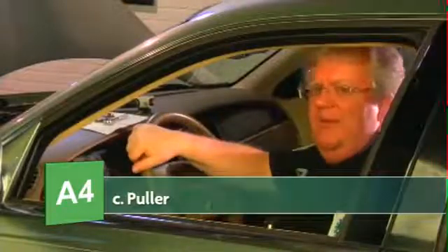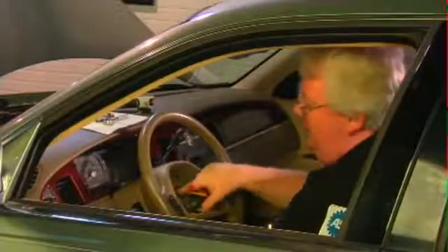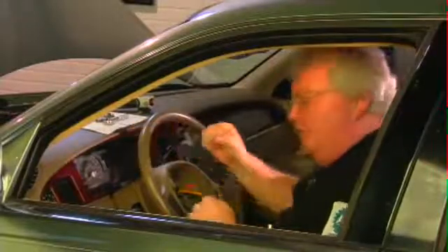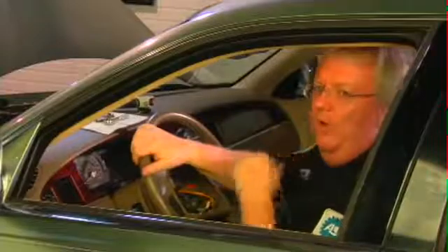Now it's important to read the manual. The manual is going to tell you this is a bolt that is to be discarded. So it's a torque-to-yield type of bolt, where you use it once, torque it, and when you remove it, you throw it away and get a new one.